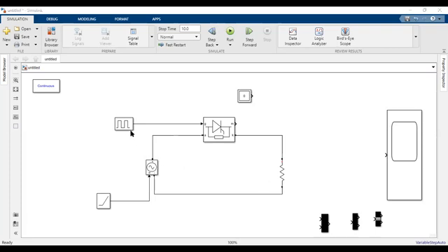Okay. The gate pulse, that is the pulse flowing from the pulse generator through the gate. We'll measure this one, number one. Number two, the input voltage, that is the voltage from this control voltage source. Number three, the thyristor voltage, that is basically the thyristor parameters. We'll be getting two parameters from the thyristor. Number one is thyristor voltage. Number two is thyristor current.